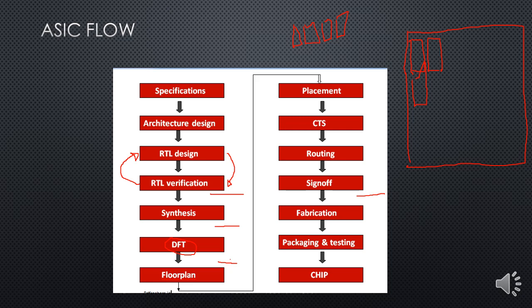I can say I have put it over here like this. It cannot be overlapped; it cannot be one over another. So it is present like this. We have placed all these 4 macros here. Placing these macros in my chip is what we call floor planning. This is one of the important steps in physical design. Most of the tools take the floor plan as a reference, and their algorithms are based upon that. That's why floor planning is an important step involved in the PD flow.